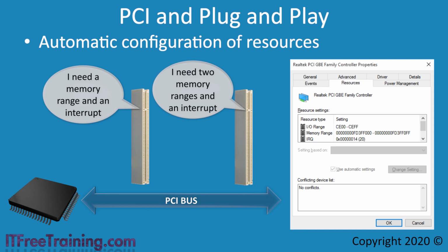The memory range is generally a lot larger and so is used to transfer data from the expansion card to the computer. Essentially, the I/O range is used for control. Memory range is used for transferring data. However, the manufacturer is free to design and thus control the expansion card however they see fit. The computer just needs to ensure that it has allocated enough resources when requested.